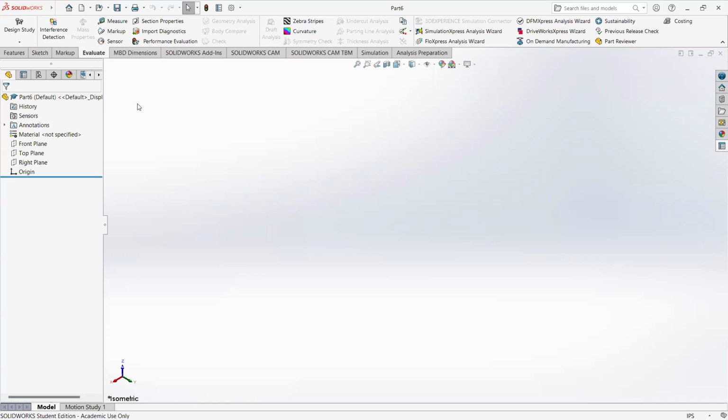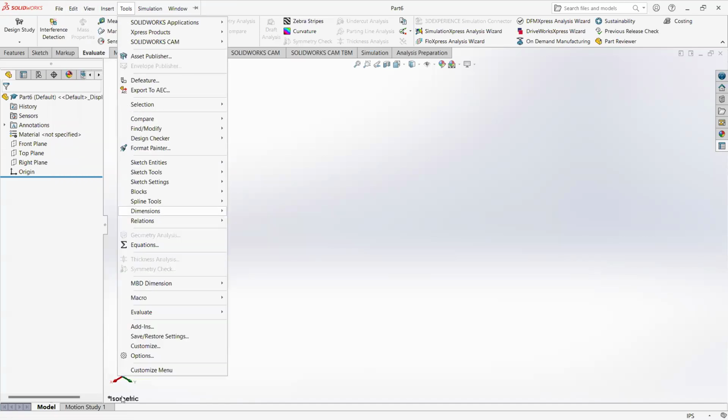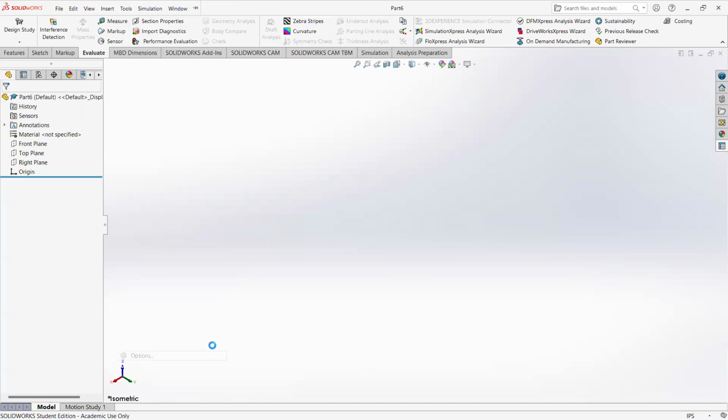But you can change it document by document just by going up to the menu and Tools and way down at Options. Now, you could change this at any time. If you do, and there are a lot of features in this model already, this list will be much longer and you may have to scroll down. There'll be a little arrow down here to scroll to the bottom, but it's always under Tools and Options.